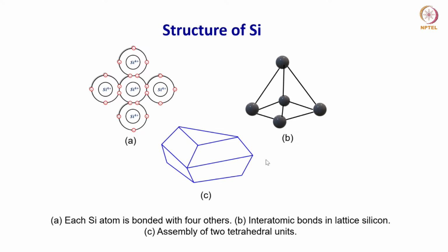That means I am talking about the eutectic reaction as it happens during the solidification, as you cool the alloy from the molten state. Okay, so you need at least two of these units, two of the tetrahedra to form a stable nucleus of the silicon, and then as you pull it down more and more, this is going to grow.